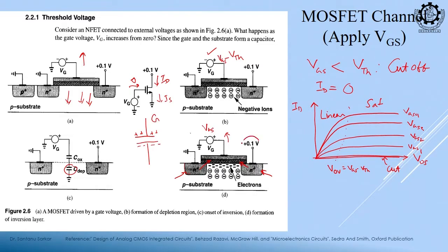And now, if you put a positive potential at the drain, what will happen? The drain will collect and the source will act as if it is sourcing the electrons. Clear? So, as electrons flow in this direction, we say current is flowing in the opposite direction. This is the working principle of the MOSFET.